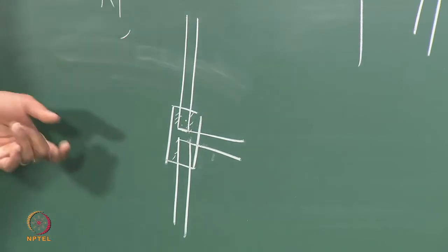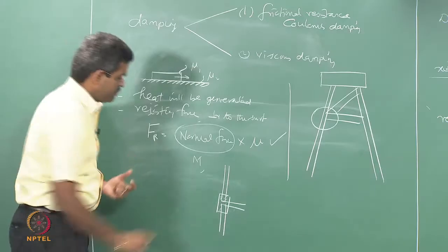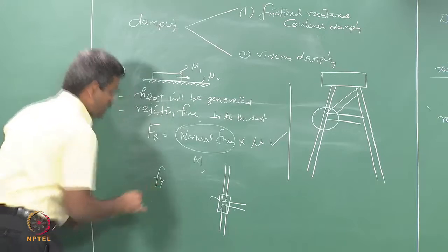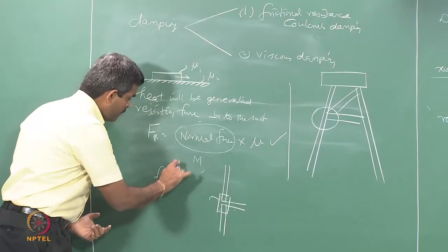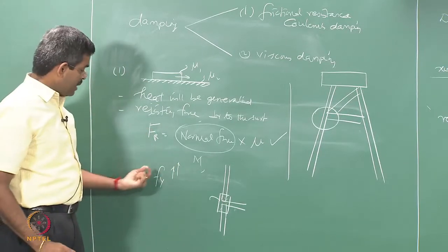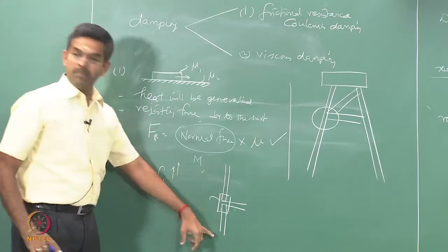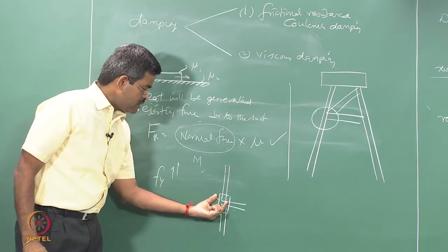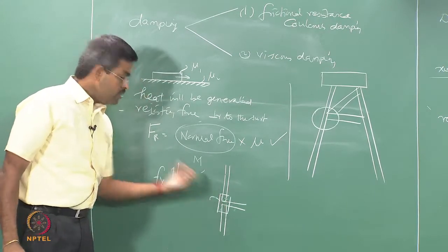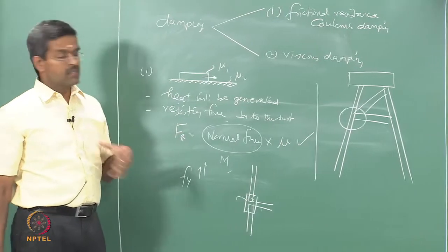You will all agree that the material strength or the characteristic grade of steel used in this connection is far higher compared to the characteristic grade of steel used for the members, because joints or connections are subjected to a high stress concentration factor in offshore structures.